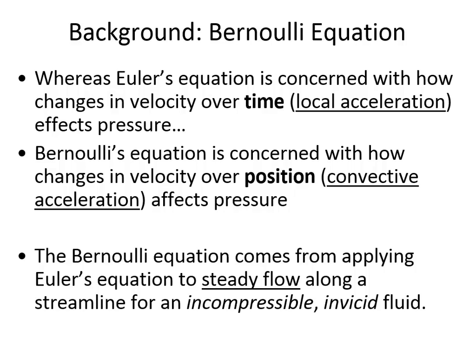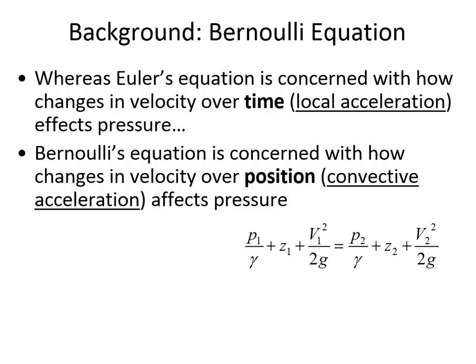But in an enclosed system we had another example where we didn't cancel out those terms. When we had a U-tube that was sealed and water was all the way up to the surface, remember this was 1 and this was 2, and we didn't cancel out the pressure head terms in those problems. And the same thing will be true when we're working with Bernoulli's equation.